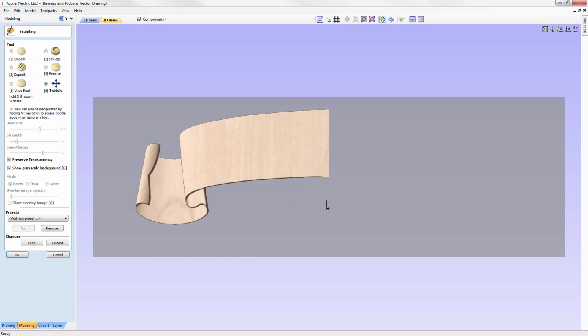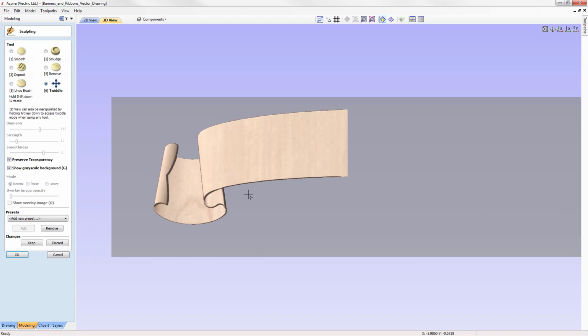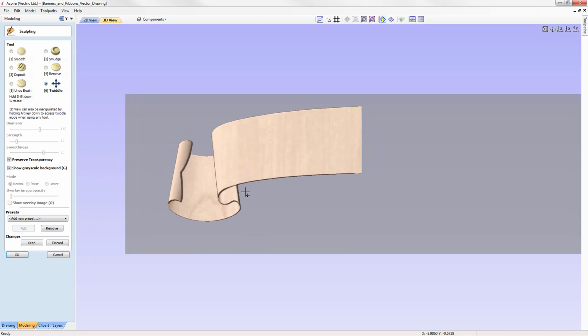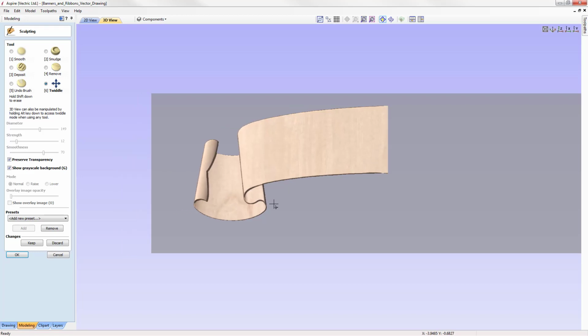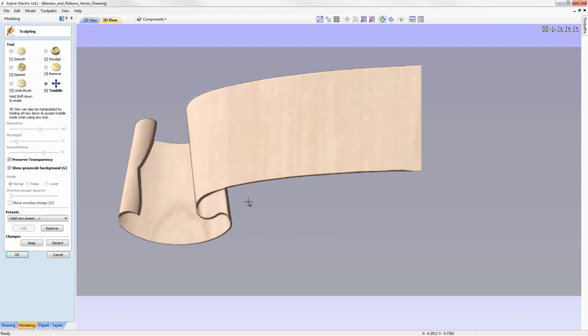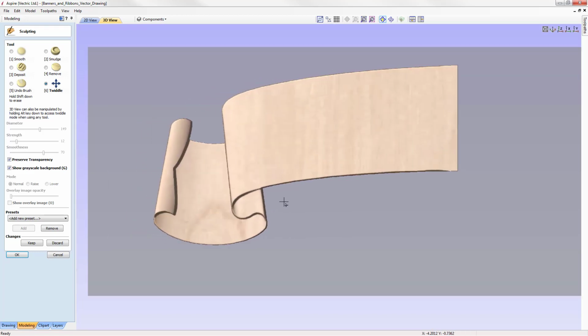So if we go into our twiddle view, and then if I press both the left and right mouse key down and move over to the right, you can see I'm able to pan my view. And then using the scroller of my mouse, I'm able to zoom in. Okay, so I'm just going to make that more central just so I can really see what's going on here. And then what we can do is we can go into the smudge tool. And so the smudge tool enables us to pull and push material as if it were virtual clay.